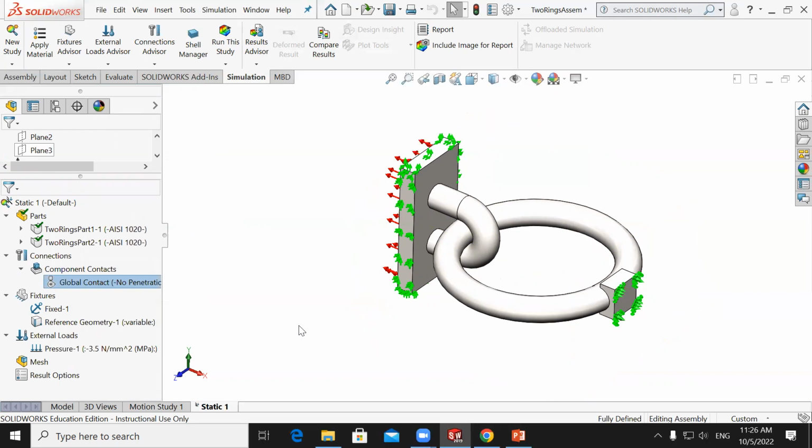And in this one, we use mesh control. The last one we have done, the first one, was just global mesh, with a set ratio that tries to create mesh in the areas concerned with stress concentrations, not using a mesh control. But in this one, we will control the mesh in some area that we think is really important.